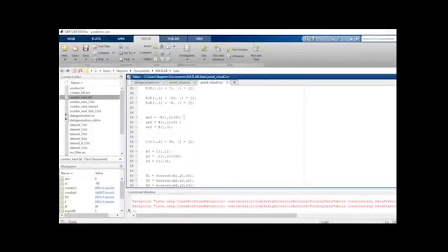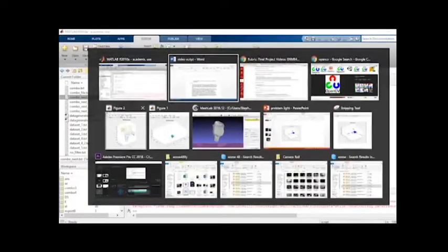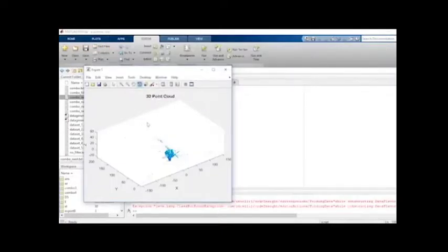I can also use addition and subtraction to translate the datasets, which I have also done here and to the other datasets. Since I know the orientation and distance of the object for each dataset, I was able to combine the datasets into one point cloud without too much trial and error. So this is what the raw point cloud looks like. As you can see, there are a lot of extraneous points and a lot of noise.